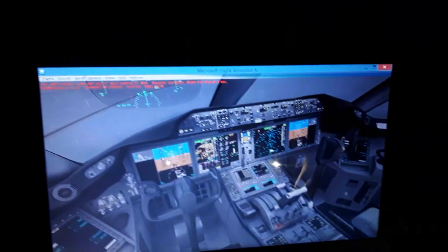Also to use the rudder pedals to make coordinated turns in the air using the rudder, the vertical tail section of the aircraft. I have also interconnected on the ground the nose wheel steering, which is interconnected with the tiller, so I can use the nose wheel of the aircraft for making left and right turns. Also the rudder pedals, toe brakes. I have also the thrust levers, the horizontal trim stabilizer, the flaps and the slats, the speed brakes. So I have all the flight controls of the aircraft in flight. So I can apply also the thrust from the engines.